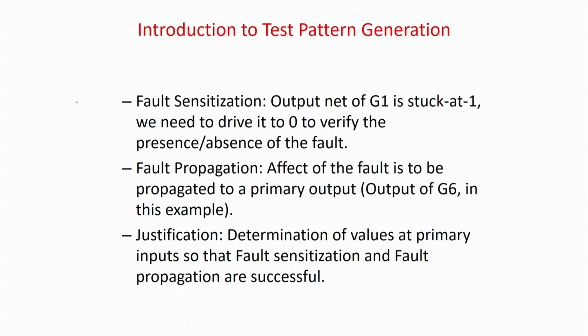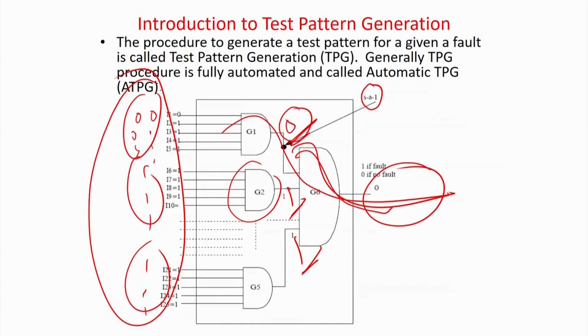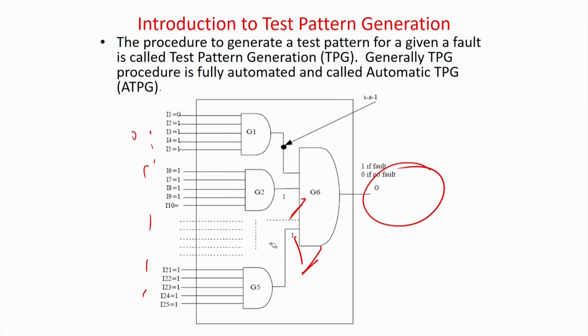But it is not as easy as that, as there can be a lot of conflicts. If there are conflicts, we have to apply different test patterns to solve it. I will take an example. In this case, for justification I require all ones over here. So, there is only one solution, all ones over here, but I require a 0 over here. How many different patterns can be possible for this gate? It can be all zeros or it can be 0, 1, 1, 1.